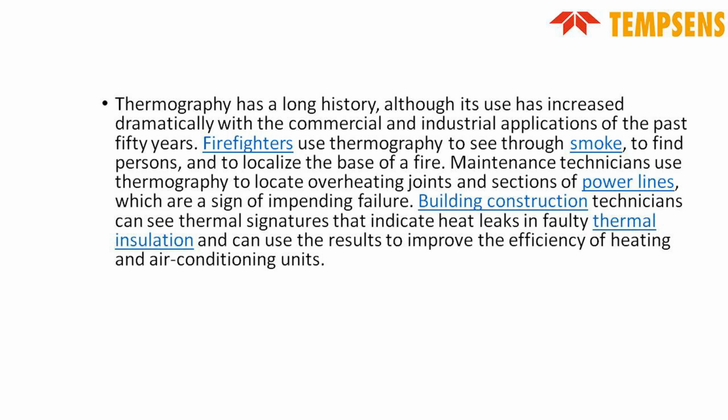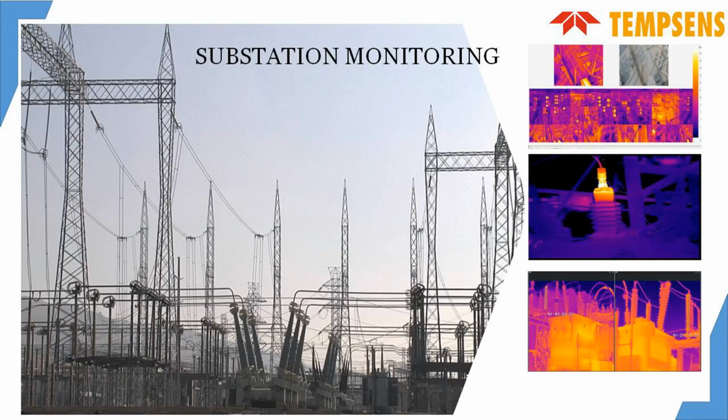Now, the first industrial application is substation monitoring. A substation is basically a part of the power industry where there are a lot of electrical equipment like power transformers, current transformers, circuit breakers, conductors, isolators, and insulators. All of these need to be checked regularly with the use of thermography, because if any of the equipment fails, then power distribution gets affected, or eventually it can turn into a blackout for the entire city. So complete monitoring of these substations is very crucial.